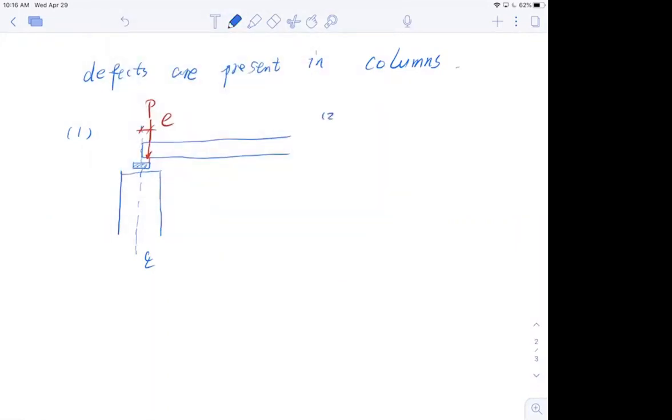The other scenario, right? What if, when I fabricate my column, my column is right here, section-wise, and my reinforcement is supposed to be located here? These are my 4 corner bars. But unfortunately, I'm gonna have an eccentricity of my reinforcement that messed up the whole thing.